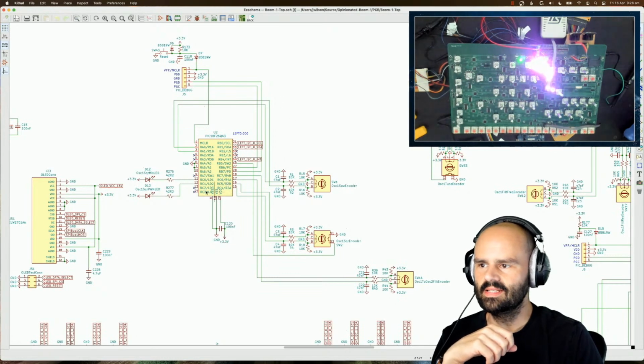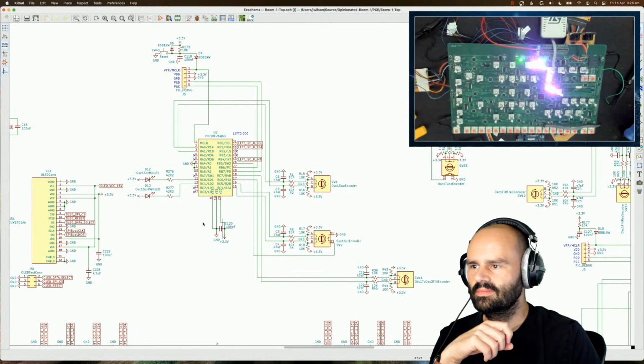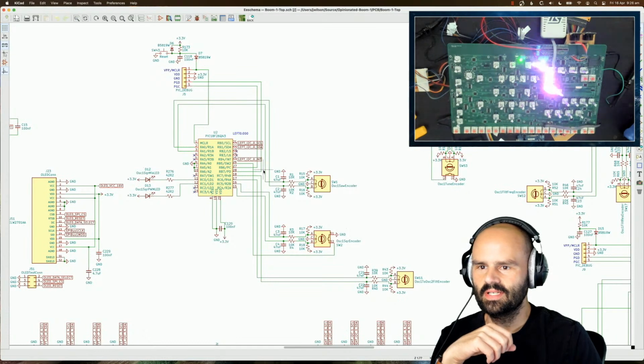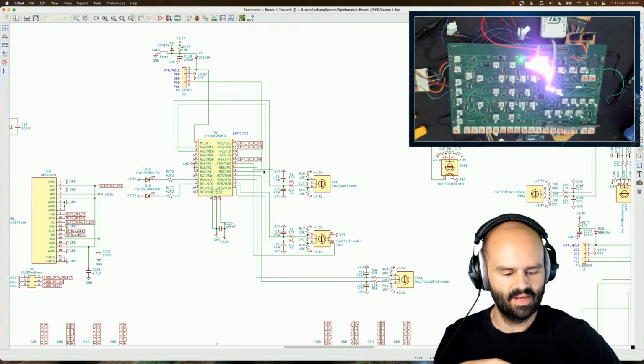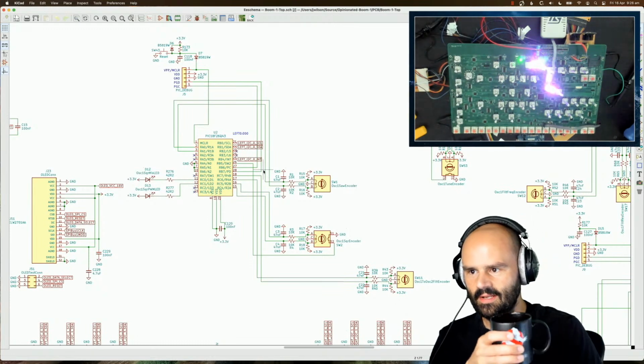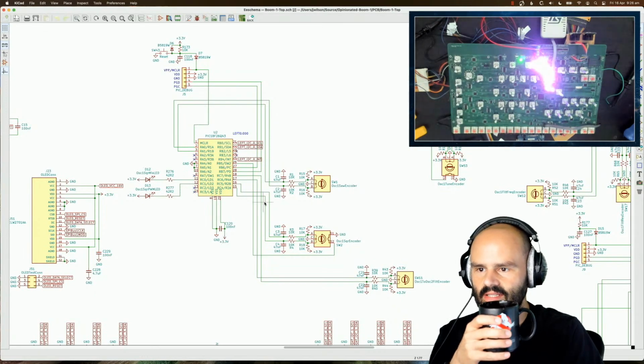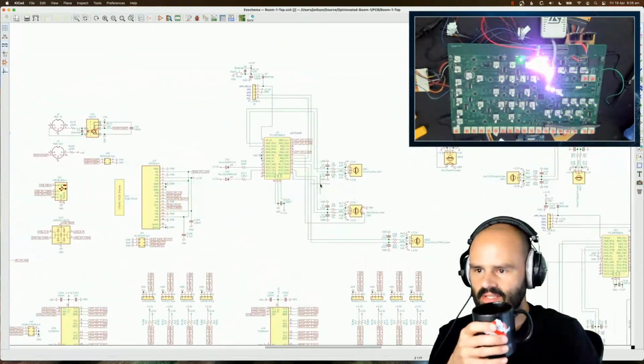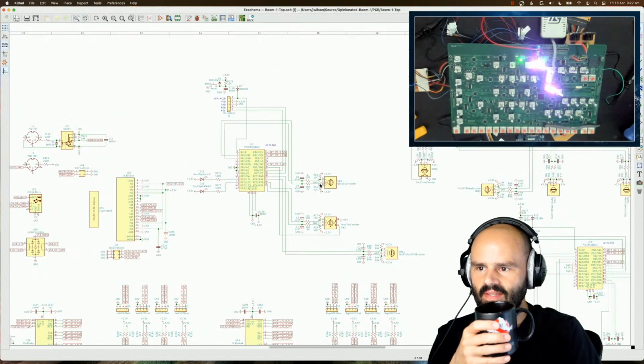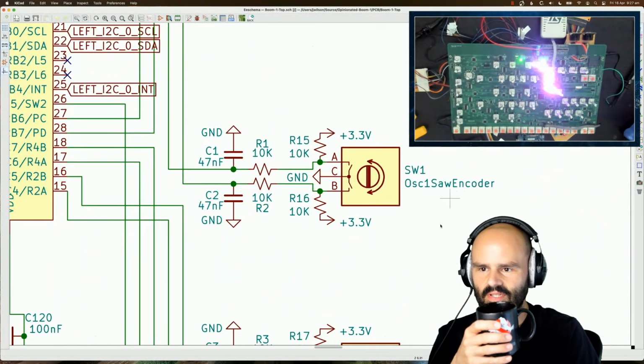And the PIC is this lovely little chip created by Microchip Technologies, and it's essentially a little programmable CPU. You can write code, you can upload the code to it, and it does what it does. The reason I chose these is because it has these things in them called CLCs, customizable logic cells, which allow you to set up a couple of little simple gates that understand the way in which these encoders work.